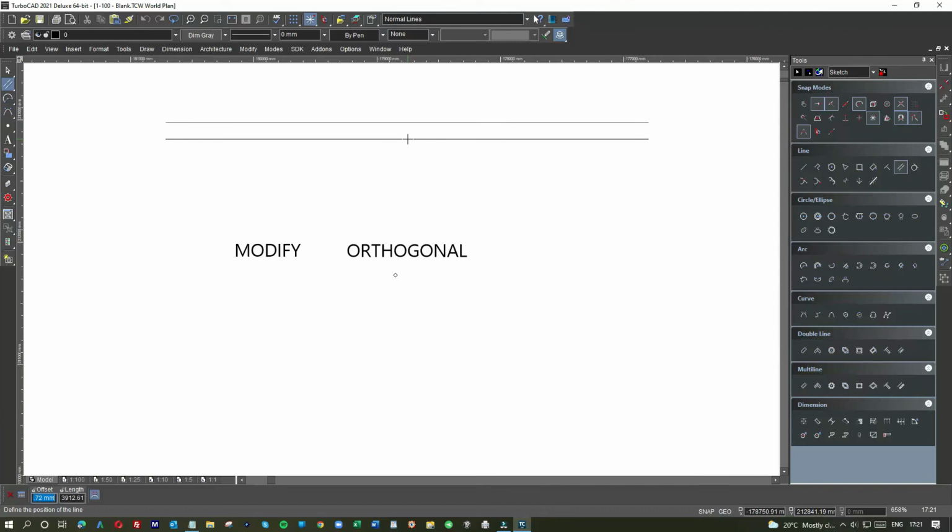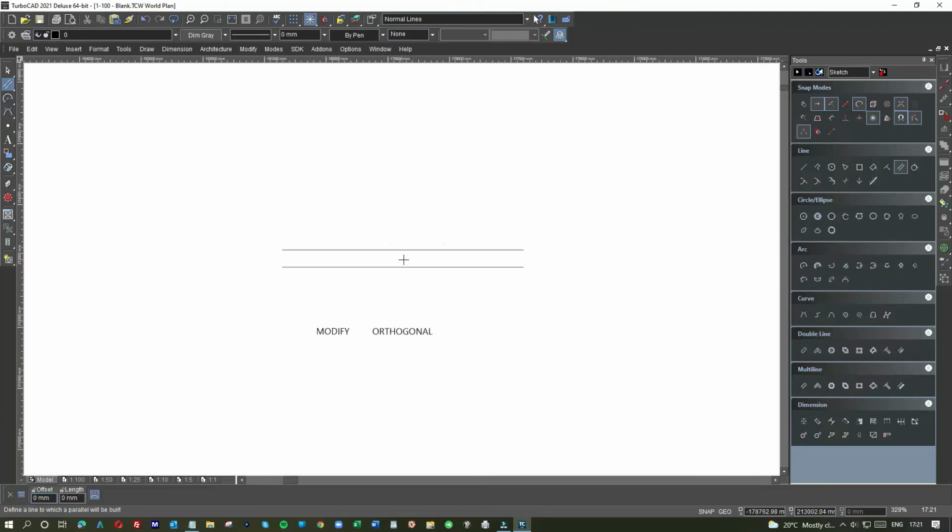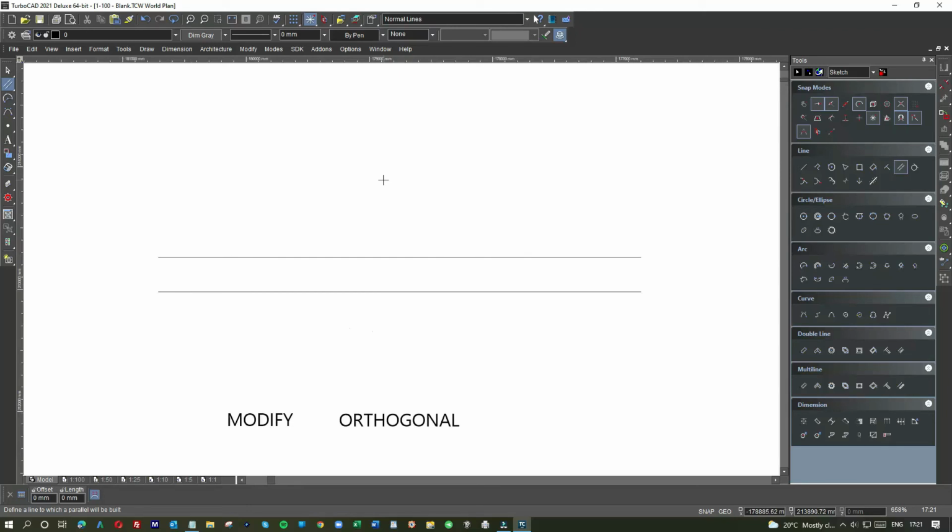I'm going to tab 280. It's an outside wall. Now let's assume I want to put a door in there. The door is 762, which is a standard interior door, plus 100 for the frame, so 862. So I just go like so, tab 862, tab 862, and I've got me a box with 862.